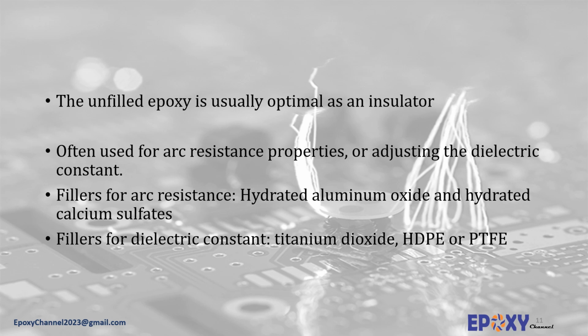Also, under conditions of high humidity, fillers may tend to wick moisture and considerably degrade the electrical resistance properties of the adhesives. The one exception where certain fillers can provide electrical property improvement is in arc resistance.